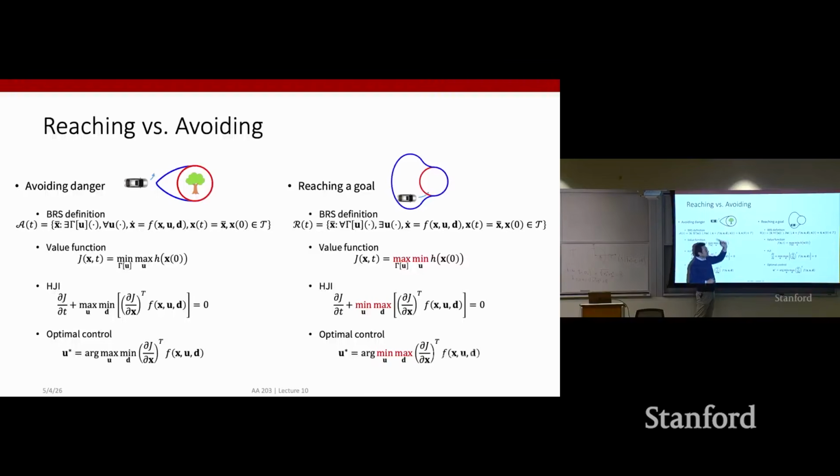So for your state to enter some unsafe region for some adversarial selection of this turbulent profile, the problem that you want to solve is a minimax problem. We already discussed how to pick H, and then there is nothing else that you have to do. You just write down the Hamilton-Jacobi-Isaacs equation for this specific problem. Same as last time, we don't have the running cost. And of course, for the boundary condition, we use the H function that represents membership to a given set.